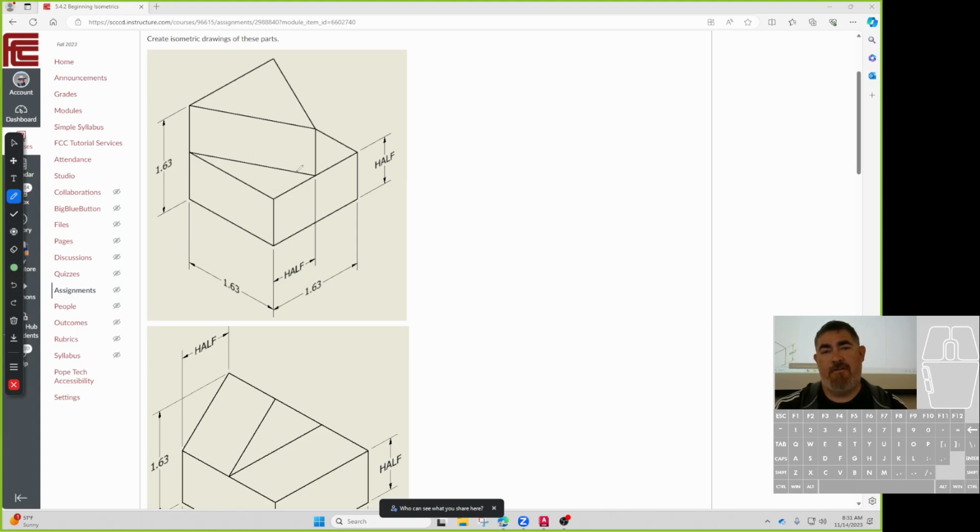So in order to get this line, I have to kind of find the endpoints of it. So if I find this point, I can just come from here and go up halfway, right? Or draw this line and then go from halfway there. But if I come over and I draw this line along that way, the 1.63 that way, and then I draw this line going this way, now I can find that corner and I can connect the dots. Just polar tracking, right? Yeah. So in order to do this, I just need to kind of triangulate where that other corner is.